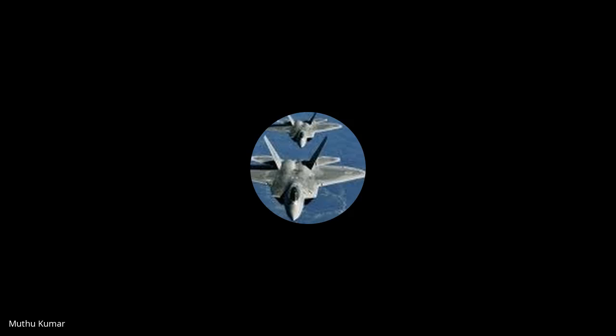So let's see how to understand the slope. For an alpha, this is the CL. If alpha increases, the CL increases. So I call this graph CM versus CL. What is this CM? This is the pitching moment about the center of gravity of the aircraft, and I plot this with respect to the coefficient of lift.